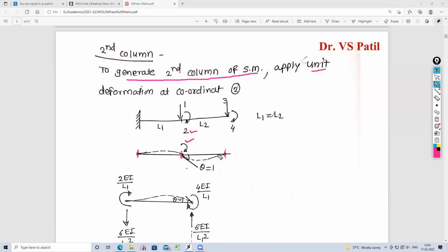Then on the second part, the moment is acting from the top. Therefore, it will sag like this below. Okay, and then the same is to be applied on the second part, so the moment is acting from the bottom. Therefore, the first part of the span is going to hog like this.